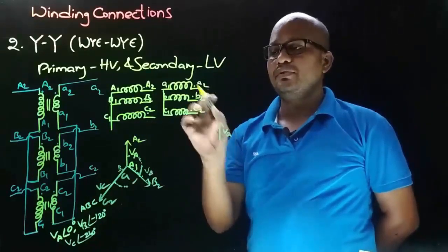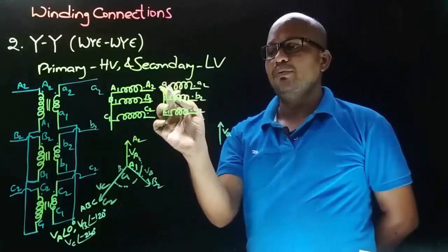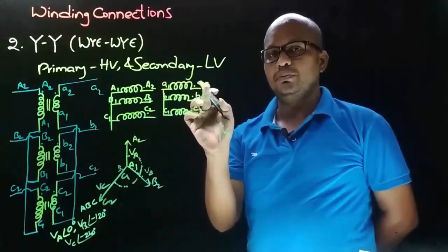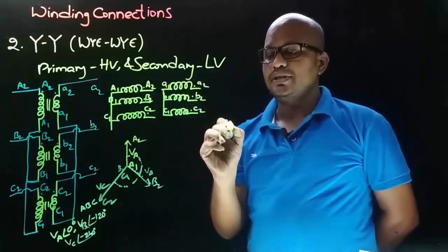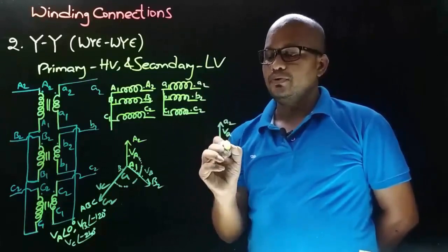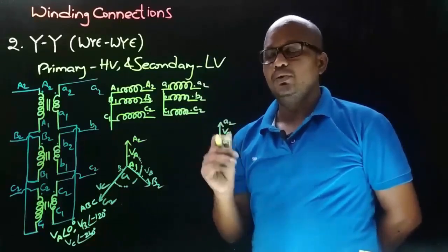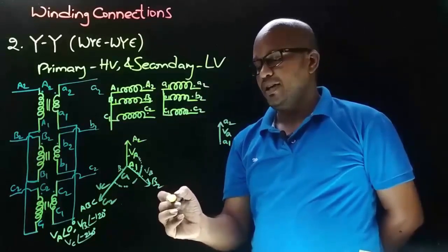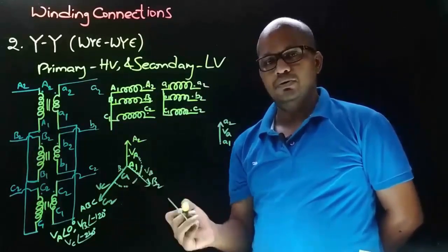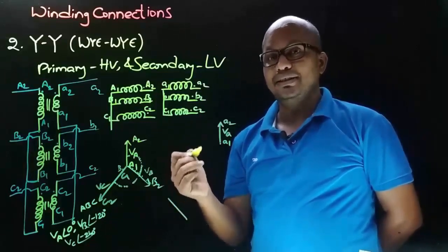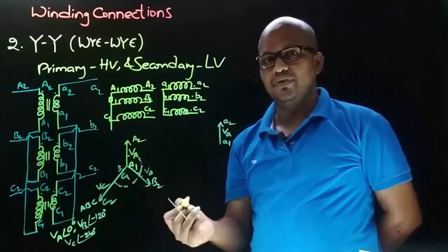So terminals of VA is A1 and A2, and here we took the connection from A2, means arrow points towards A2 because connection is took from A2. So this will be A1 terminal. And now let's draw the VB phasor. So first let's draw the phasor parallel to primary side VB phasor, and now we need to decide the direction of secondary side VB phasor.